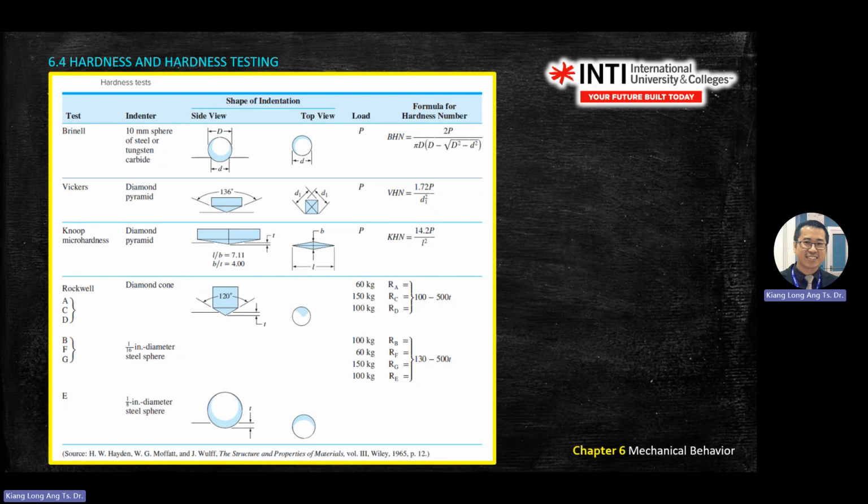If the indenter is round, like a Doraemon hand, you press and you'll see a sphere shape on the surface. You press with a round object, you'll see round things. So if you're using a round indenter, the test is called Brinell.